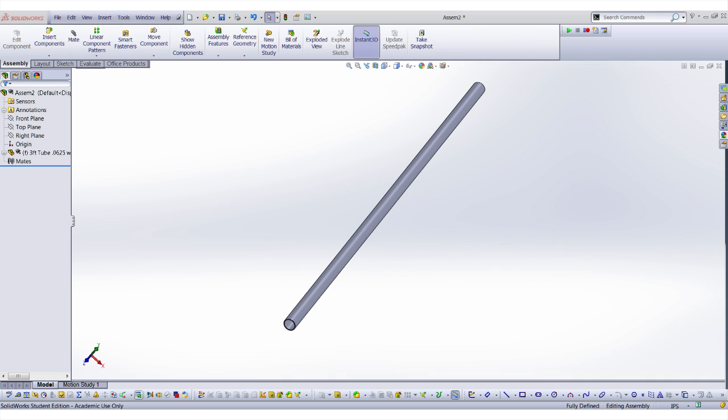Try to center it on the face if possible. There's numerous different ways to do that, actually. You have to center it on the part? Yeah, you should try. Since you know the face is a 5-inch square, you can use the Smart Dimension tool and dimension off the outer lines of it to the center of the circle by 2.5 inches. You could draw construction lines and make an X, and then it'll give you a point that you can drag to.